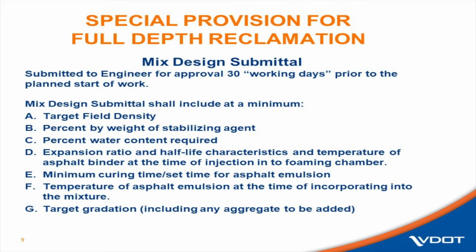So the mix design submittal is a very important document. This document really guides the entire mix design process. Important to note, it has to be submitted to the engineer, VDOT, 30 working days prior to the start of work. So that's 6 weeks. A lot of time to build into your schedule.